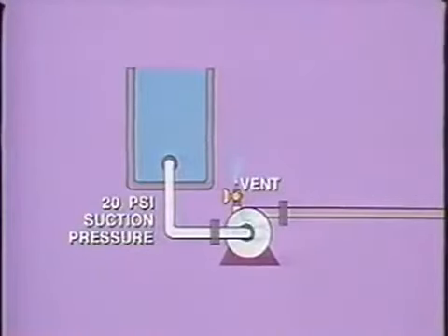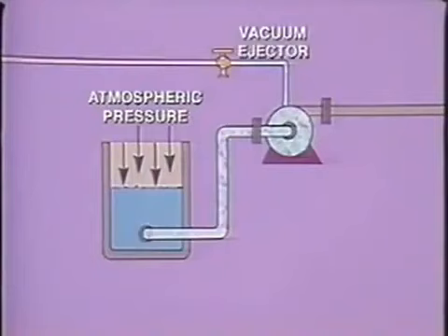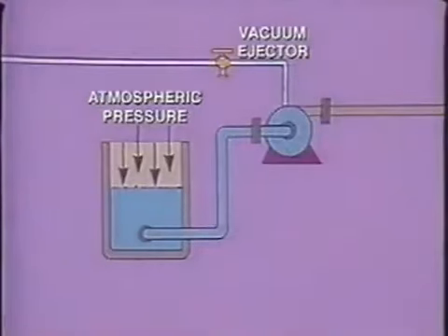This allows the air or other trapped gas to be vented out of the pump and the liquid to fill in. If the pump takes its suction from below, the pump can be filled by some sort of vacuum-producing device. As the air or gas is removed from the casing, the liquid will enter as a result of atmospheric pressure. This is similar to drinking through a straw.